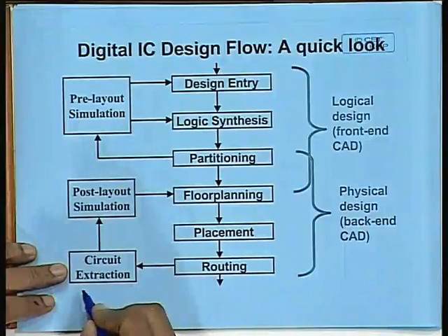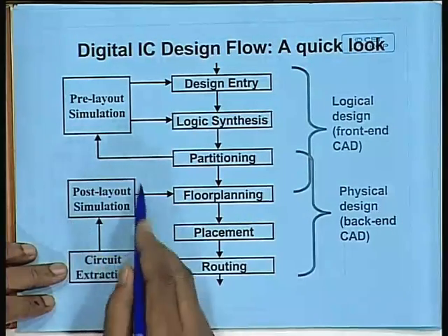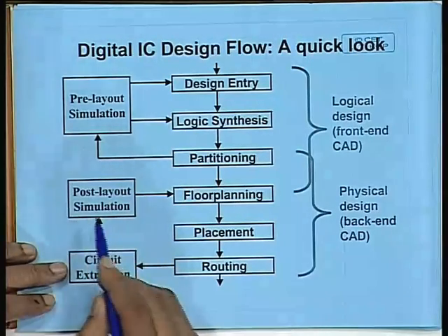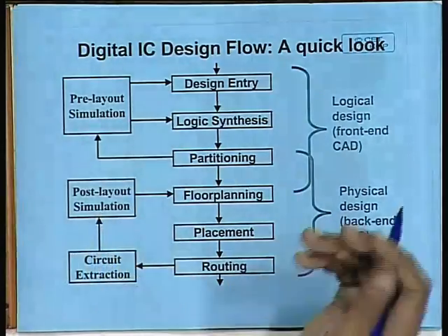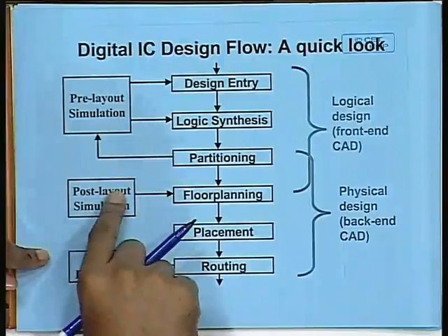So after circuit extraction you can do a post layout simulation. But the problem here is that you have a circuit which consists of transistors, resistances and capacitances. So you will have to do a circuit simulation using software like SPICE. This is time consuming, and it can only handle small circuits. So you will have to use this very judiciously.